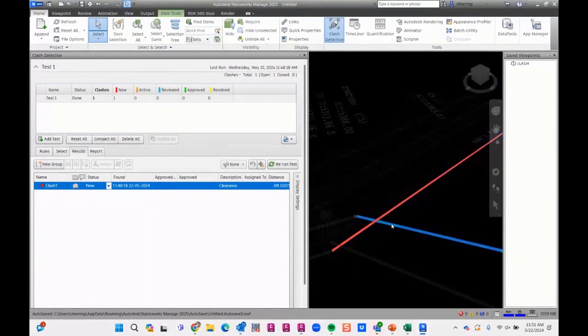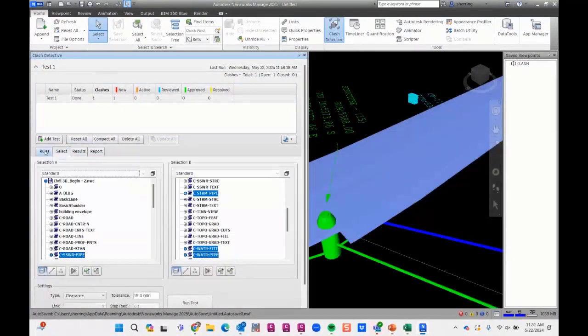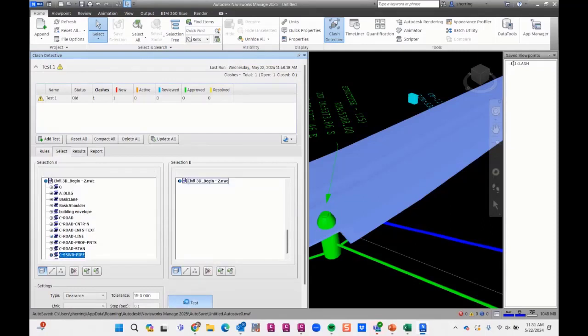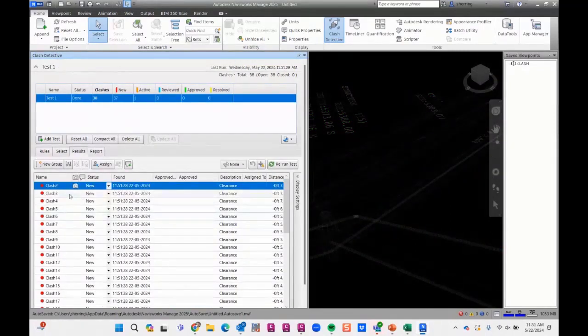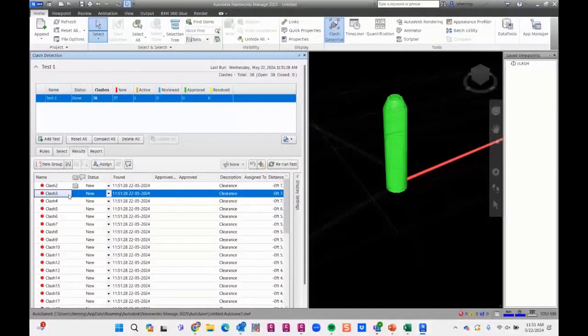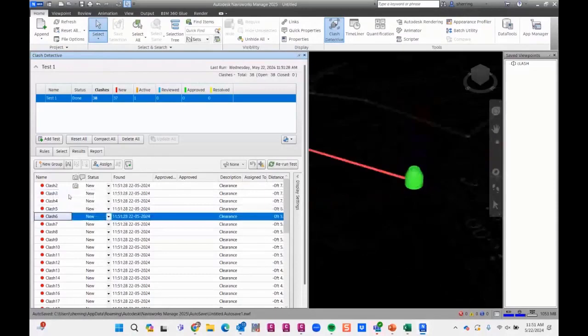So, any questions on that? You have to pick sewer, see what it clashes with, then pick storm drain, see what that clashes with. No, we could clash it all versus all or something. Yeah, because really I could clash all my sewer pipe with... let's see what happens here. Everything. But you can also pick sewer, storm, and water on both sides. Yep, to clash everything. Whatever you want to clash. Yeah, so this clashed a ton.